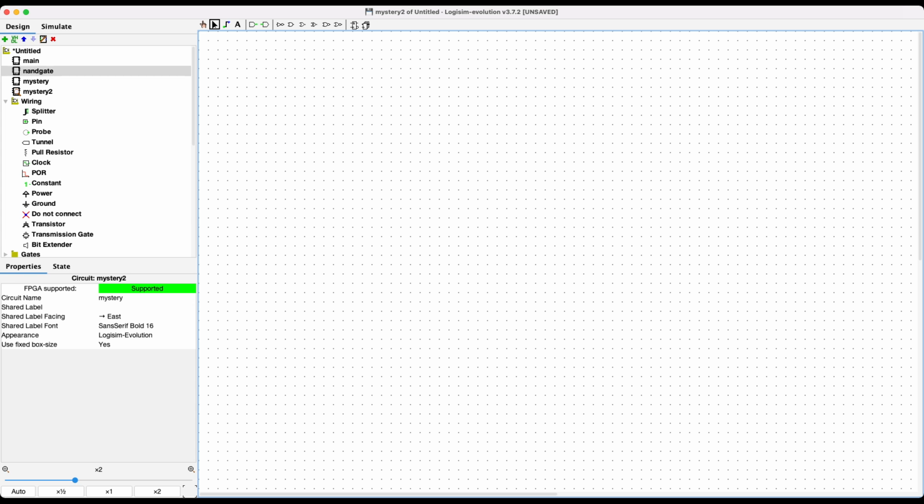What are the carries for all four of these? Yeah, okay. So I need to build a circuit that has two inputs and two outputs. One for the sum, one for the carry. Yeah? Okay, stare very closely at the sum results and the carry results. And for the sum, what circuit or what gate do I need? Huh? I need an XOR gate.